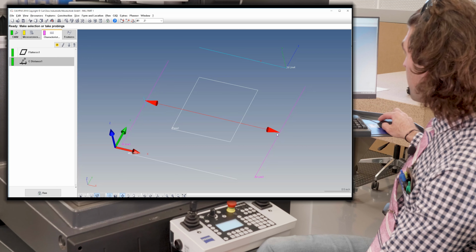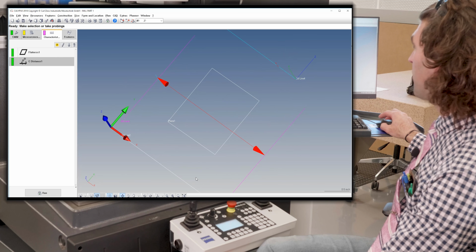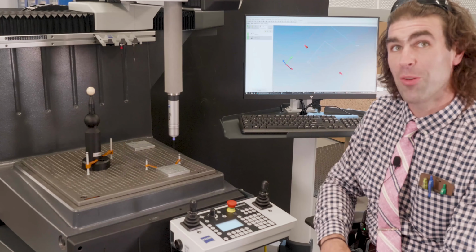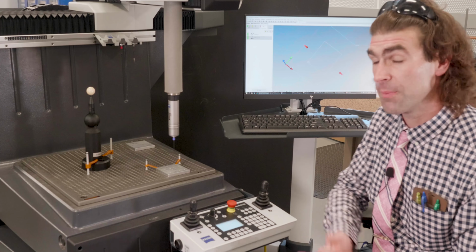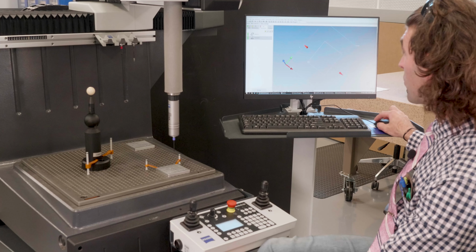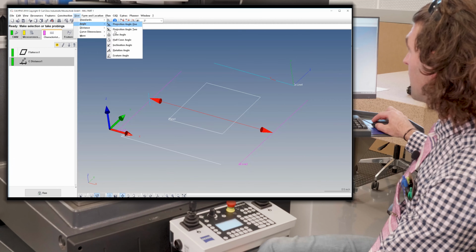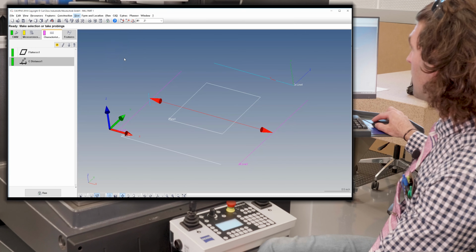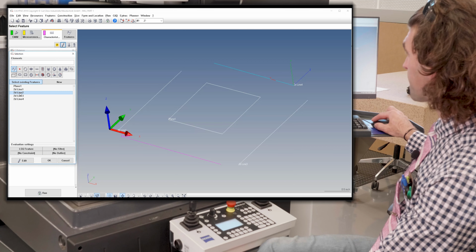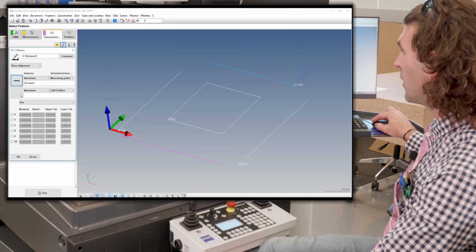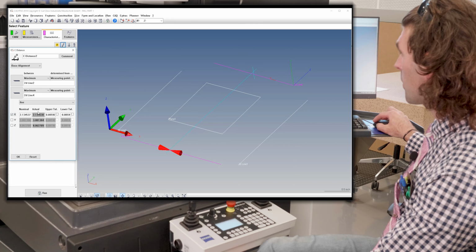And you can see visually on the screen how it's going to measure that feature, okay? So that's why I chose caliper distance. You can see exactly what the computer is doing. Now we'll measure the other caliper distance. I go again, size, distance, caliper distance. Now we want to go between 2D line 2 and 2D line 4, okay?